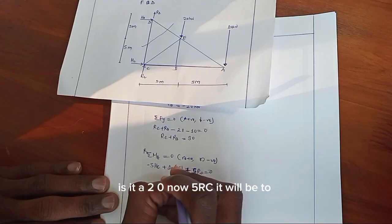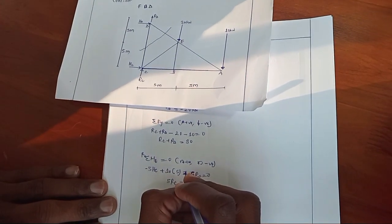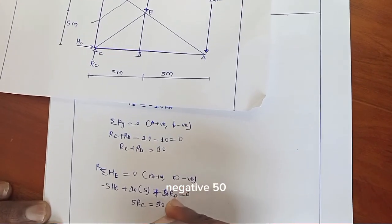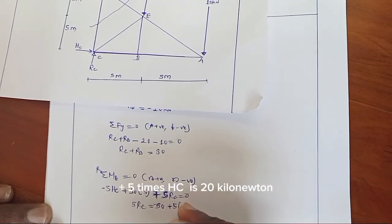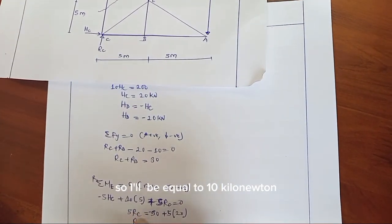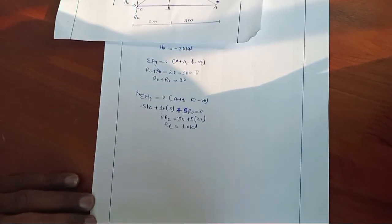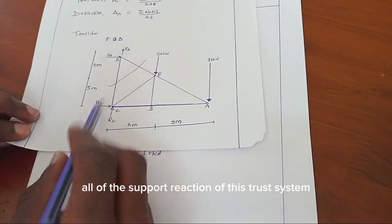Now 5 RC will be equal to negative 50 plus 5 times HC. HC is 20 kilonewton, so RC will be equal to 10 kilonewton. Now we have obtained all of the support reactions of this truss system.